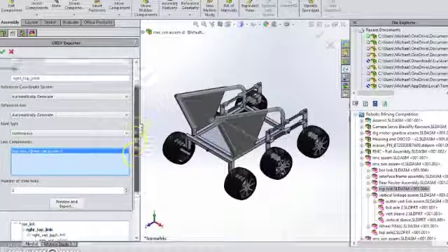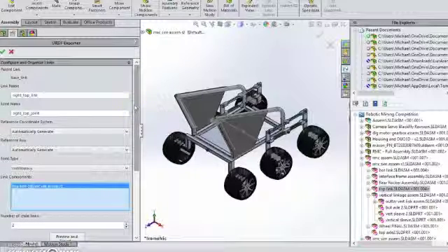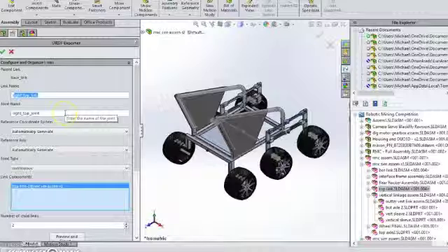So when setting up your structure here, you're going to name your links. It's nice to name it in some logical structures so that when you're going back and looking at the URDF or working on the URDF, you can kind of see what these links are, what they represent. Also remember to use underscores instead of spaces, because spaces will cause problems.